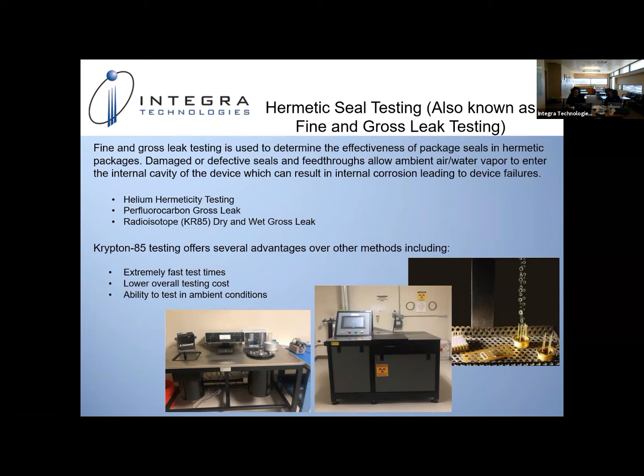And one of the other differences is the depth to which the ray penetrates. I believe EDS gives you a deeper penetration versus the XRF penetration, so you're able to get a better granularity if you do EDX versus the XRF. For finishes, you're correct. Because XRF shoots at 50 kV, it's likely that you will get underlying materials within your finish. If you're doing EDS and you're shooting at 20 kV or 10 kV, you're surely getting the finish there, as opposed to any underlying materials. Perfect.